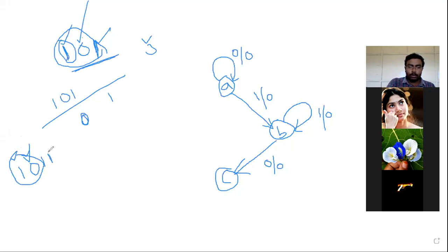Now students, the 1 and 0 are found, which is over. Now we have only one more pending bit. What is that in our desired sequence? 1. That should be found using state C here. Now you have to think carefully. There are two possibilities. If C finds 1, your sequence will be over. 1, 0 is already found using states A and B. If 1 is found, your sequence is completely over, and you can generate an output 1 here.